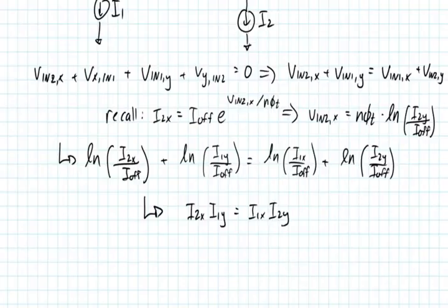Okay, so why is this significant? Well, in the prior section when we were discussing current mirrors, we found a way that we could multiply currents by fixed coefficients whose coefficient is set by the width of a gate. In this situation, we found a way to multiply two separate variables. So in the first case, we're multiplying some current, which could be a variable, by a fixed coefficient. In this case, we found a way to actually multiply two different currents.